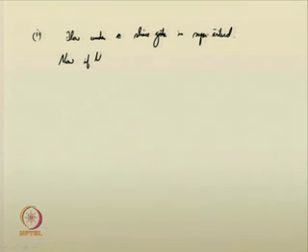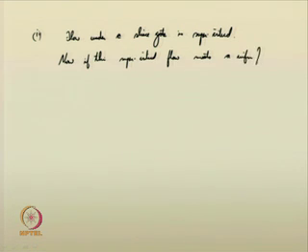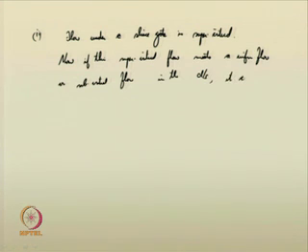Now, if this supercritical flow meets a uniform flow or subcritical flow in the downstream, it causes a hydraulic jump. So, I can just show it in the diagram.